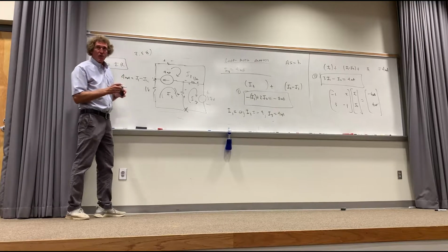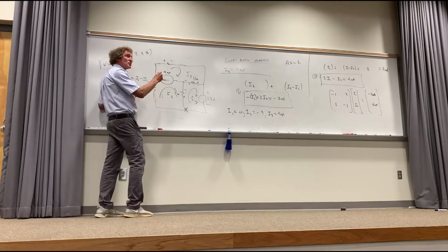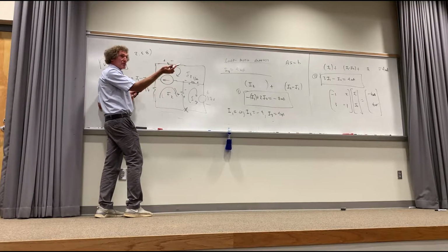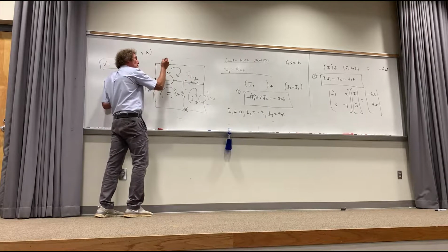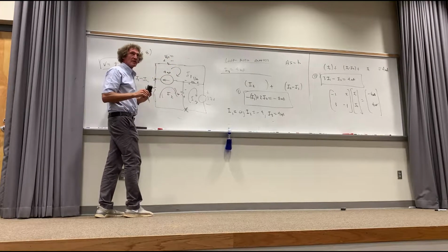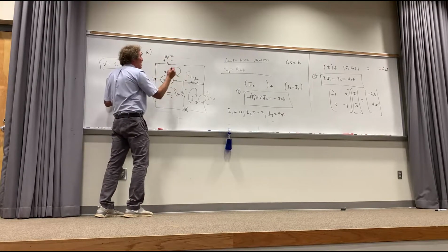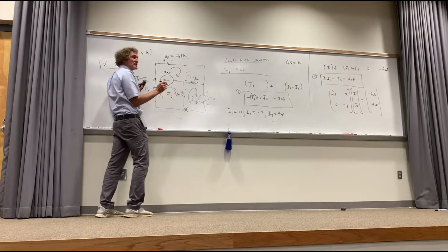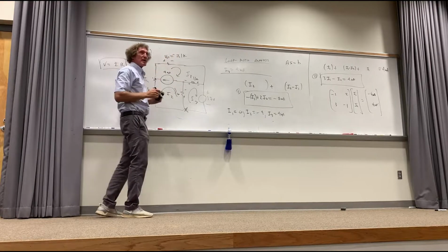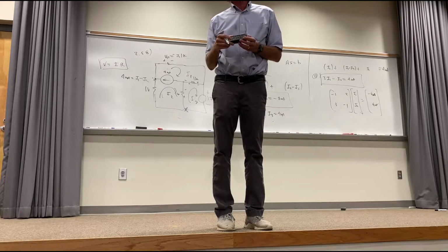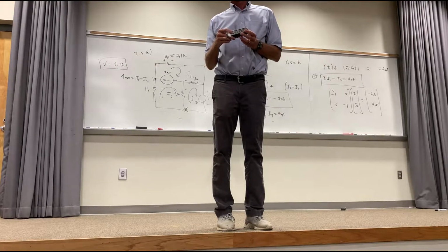I always want to get drops or decreases in voltage around a circuit if I have resistors. If I have a voltage source, I already know what its drop is, right? Or its increase. So when I put plus to minus on this voltage, VR here, well, what is that voltage? It's the net current flowing that way, isn't it? The net current flowing that way would be I1. So this voltage drop would be I1 times 1K, and the sense would be negative because it goes from plus to minus. Do y'all see that? So when I go around the loop, when I'm summing them, that would be a minus 1K times I1. All right? Follow me on this, everyone? Yeah. All right.